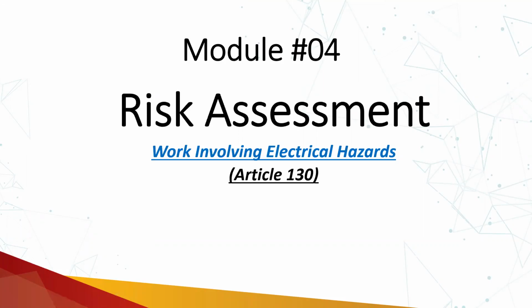So here in this risk assessment, it takes into consideration when you are performing some justified energized work, as per the exemption category given in article 110.4 A, B, C, or D. Then you have to perform a risk assessment before starting any live task.